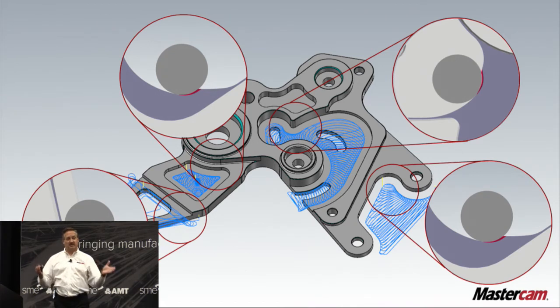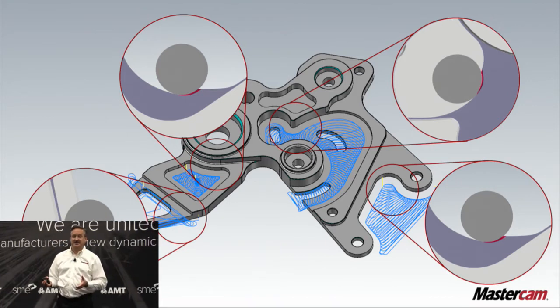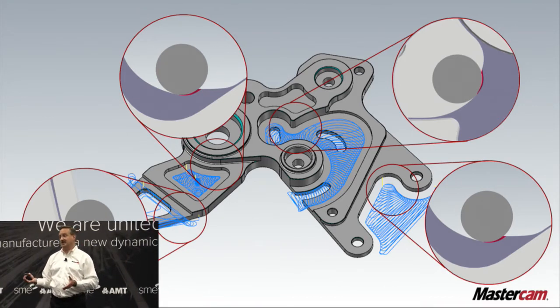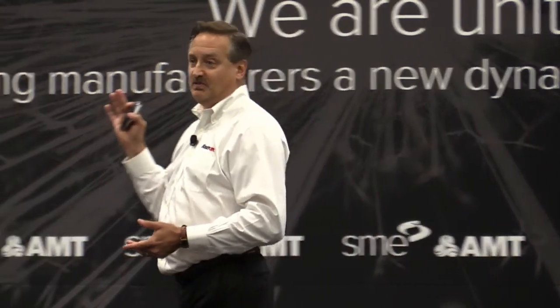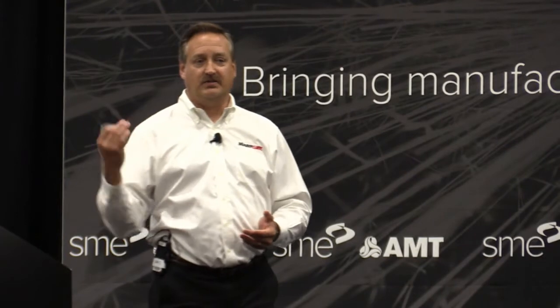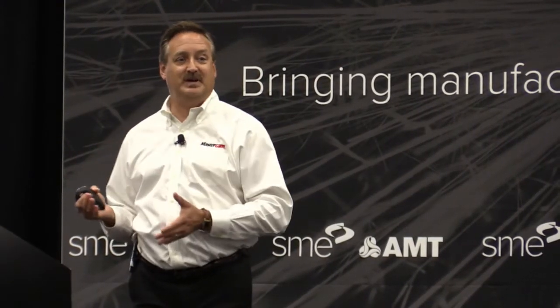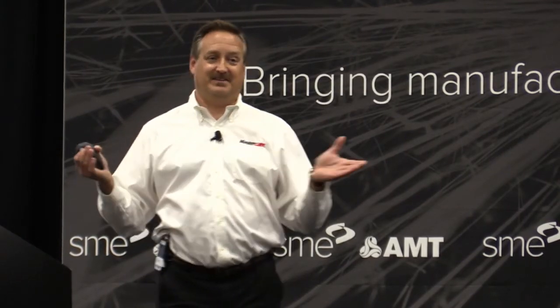Looking at the specs, we ask ourselves, why are they speccing it out so low? Well, most guys out there aren't using contemporary toolpaths. Dynamic motion is just one of them that tries to keep a consistent chip throughout the entire machining process. There are others out there. But as a tool manufacturer, what are you guarding against? The last thing I want to see as a tool manufacturer is somebody breaking my tools, because now I've got a black mark on me, all right?